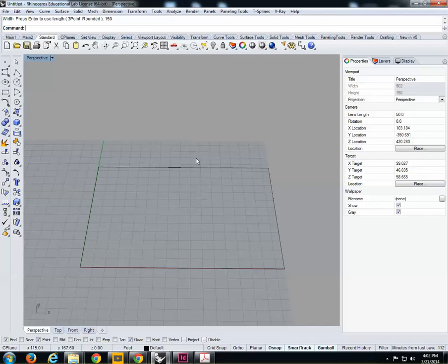Now, inside this boundary, you were asked to basically create a new curve that would be your side, your imaginative side. So you go ahead, you type curve, degree 1, as the instructions say. And why not? Let's go down here and make sure that we are snapping to the near. So we can use this boundary as a guideline for our side dimensions and save.